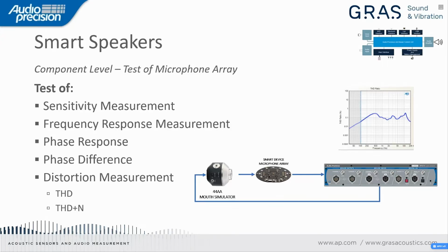For beamforming techniques, for having the right directivity and to get rid of some of the background noise, the phase response or the phase difference between each of the microphones in the array is very important. So therefore, it is important to measure the phase response as well.